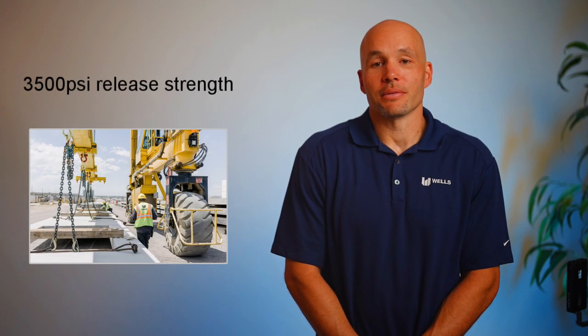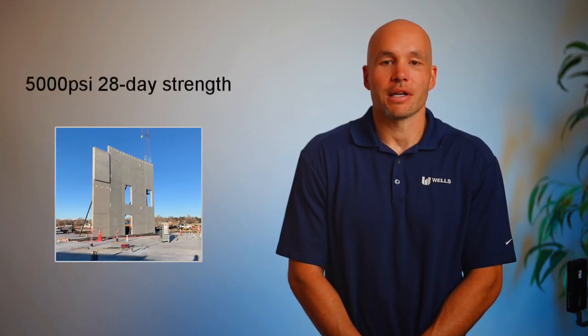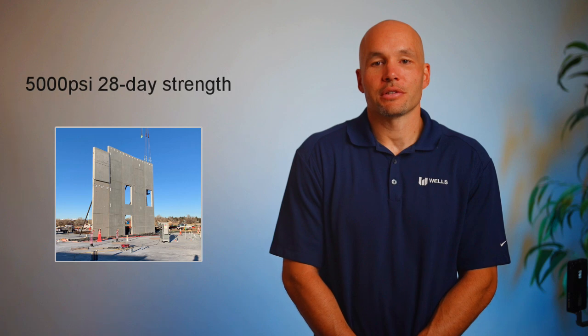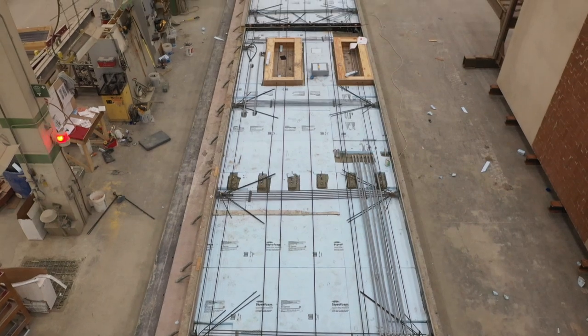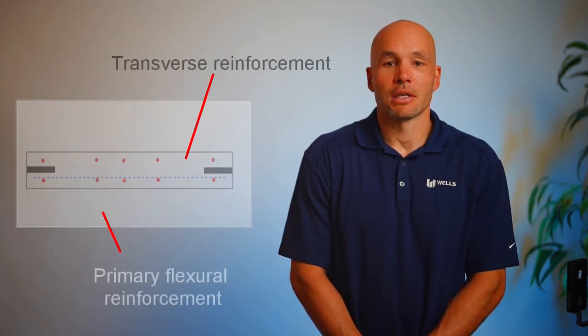Precast pre-stressed wall panels typically have a release strength of 3,500 psi and a minimum final strength of 5,000 psi. Wall panels can be subject to very heavy loads in multiple directions. The primary flexural reinforcement consists of pre-stressing cables that run along the length of the member. These pre-stressing cables develop the main flexural forces created by wind and gravity loads.